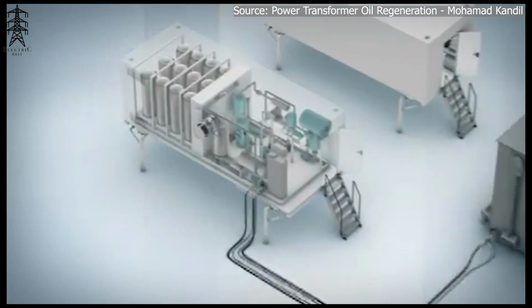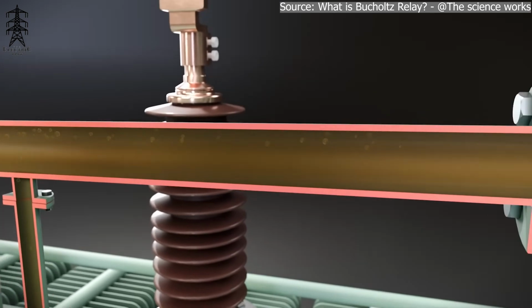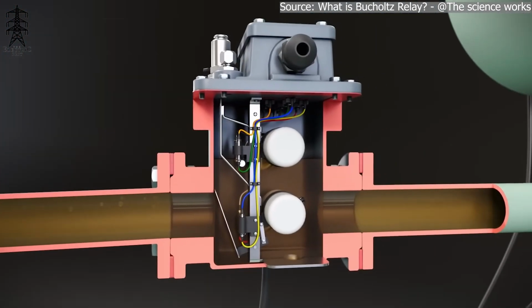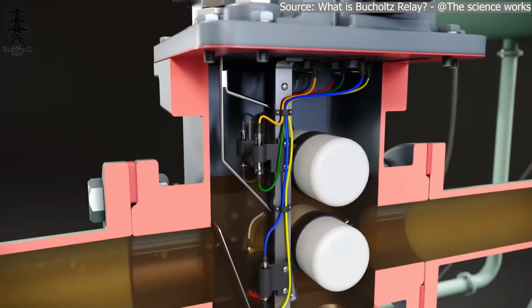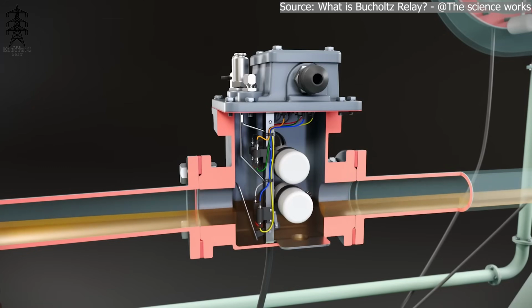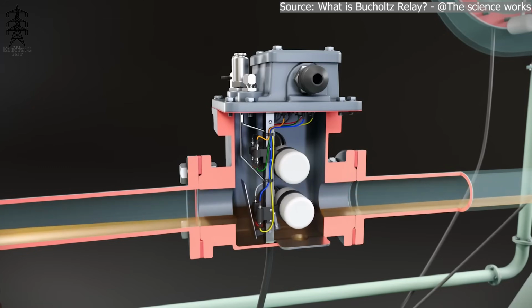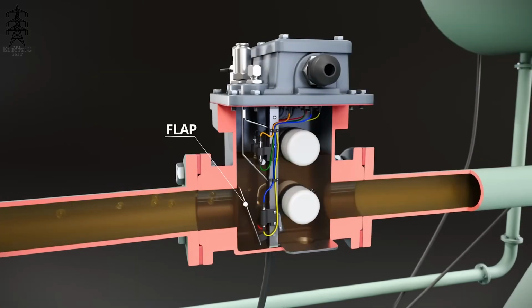If gases are produced in the oil, then the Buchholz relay located high up in the transformer in the pipework to the conservator tank will detect a rush of gas, quickly displacing the floats inside, and will trigger the protection to trip the transformer. A slow accumulation of gas over time will also trip the Buchholz, and the sight glass on the side allows engineers to measure the accumulation of gas. The relay is also fitted with a metal flap, which will trip if a large rush of oil is sensed, due to the rapid heating of the oil rising to the conservator tank.